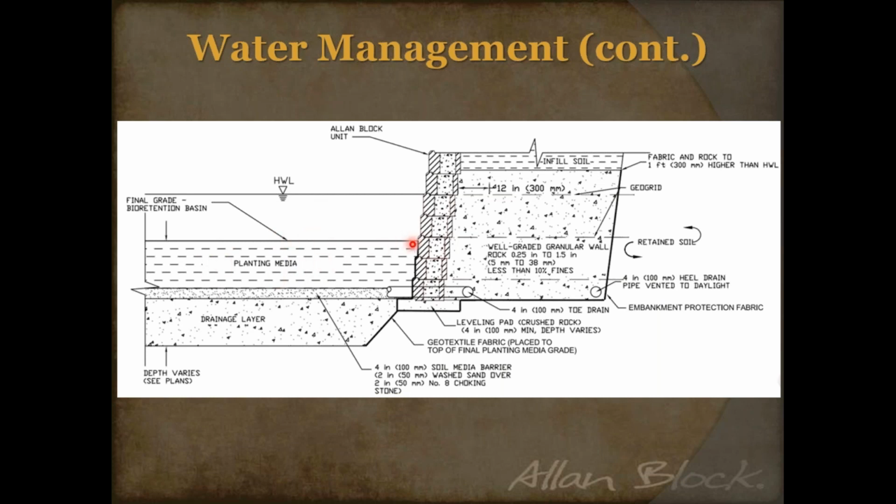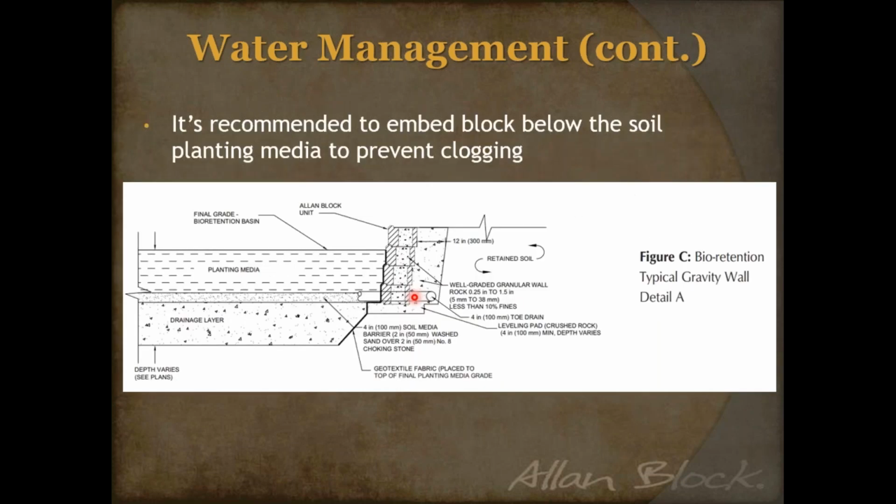Well, if this is going to get replaced, that means I've got to get my block buried below that, so we don't take that planting media as part of our embedment depth. We look at it from the sand and the drainage layer below. That is kind of like our finished grade now. That is where we're going to bring our standard embedment from that point. So for every foot of wall height, we bury an inch. We're going to make sure we bury enough block so that we're not going to undermine that structure. And that holds true regardless of the size of the wall.